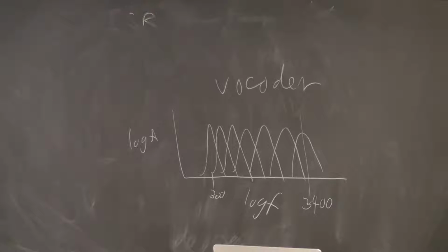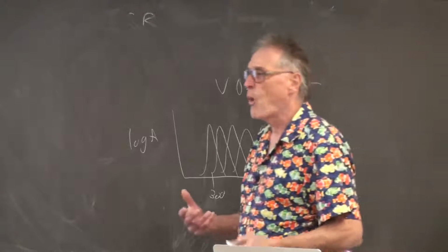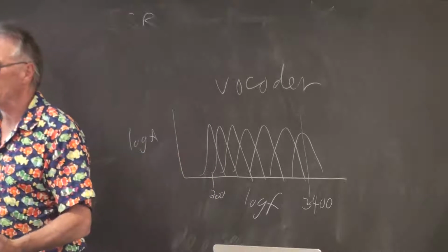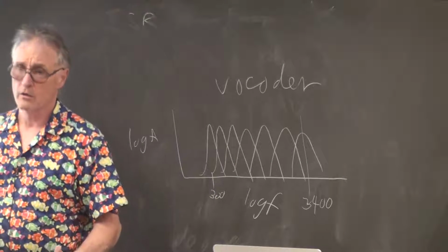So the bandwidth of your voice is 3400 hertz or so, but the bandwidth of the muscles in your throat is more like 50 hertz. About the fastest you can move your lips and tongue and throat muscles is, well, somewhat slower than 50 hertz. And so in some ways, why store all the fast information if all of the interesting dynamics are so much slower?